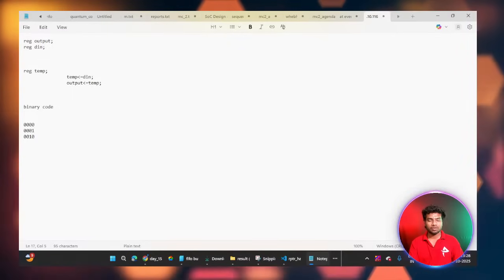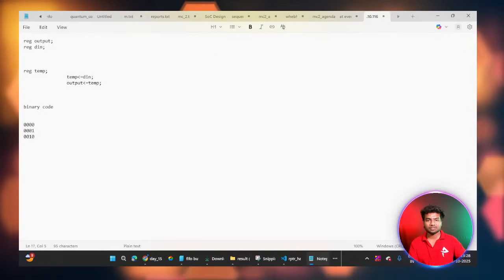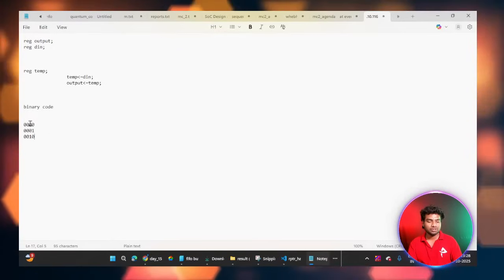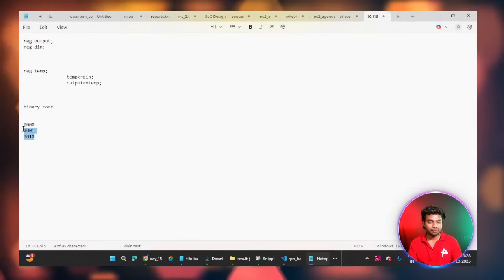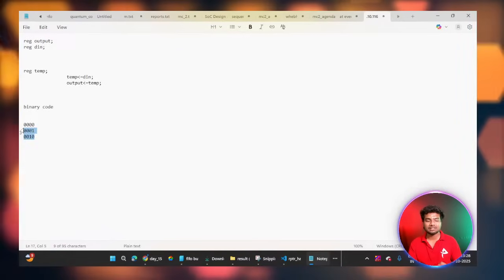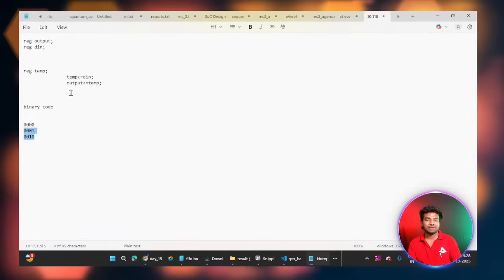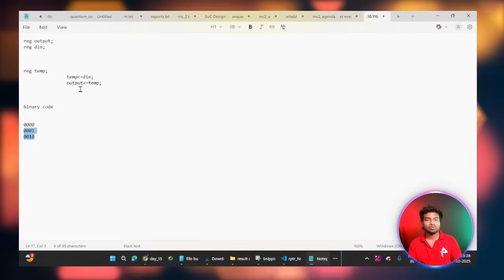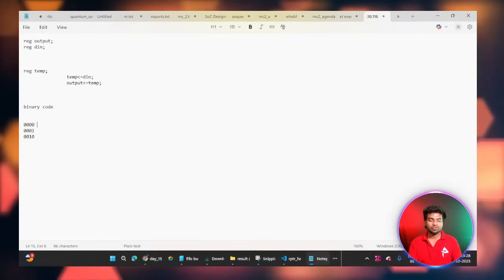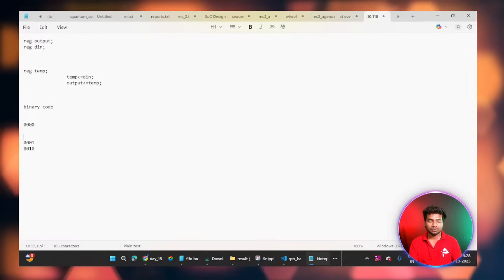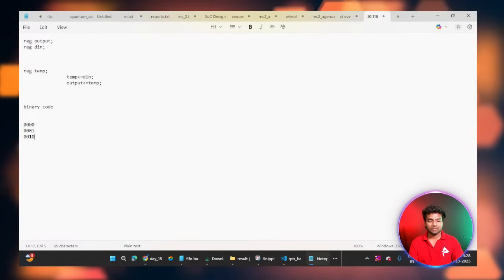This is a binary code, a binary sequence. If you use this continuous sequence of binary addresses, you will get this kind of error, a metastability error, and then you will get unknown values. So if you use gray code, a gray coded sequence...